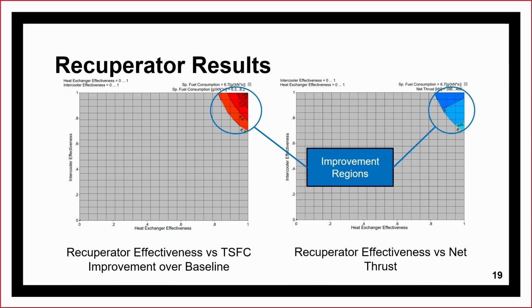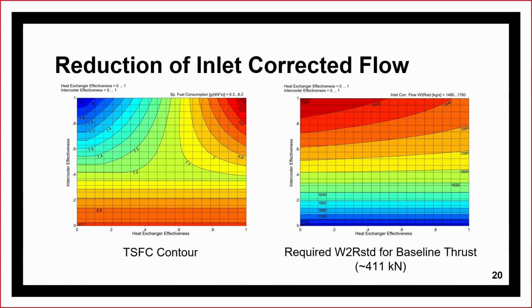Only a very effective intercooler and recuperator can outperform the matched 3-spool turbofan. In an attempt to keep the thrust the same, we opted to vary the inlet corrected flow while still investigating the effects of the intercooler and recuperator.